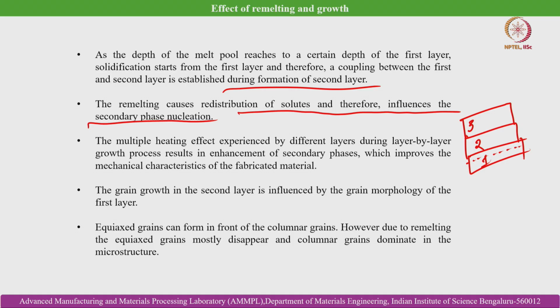However, it undergoes a homogenizing effect, because the temperature goes even higher than the recrystallization temperature, and that causes a change of the grain morphology, and also it causes precipitation, dissolution and reformation of precipitates, and also alters their size and morphology.